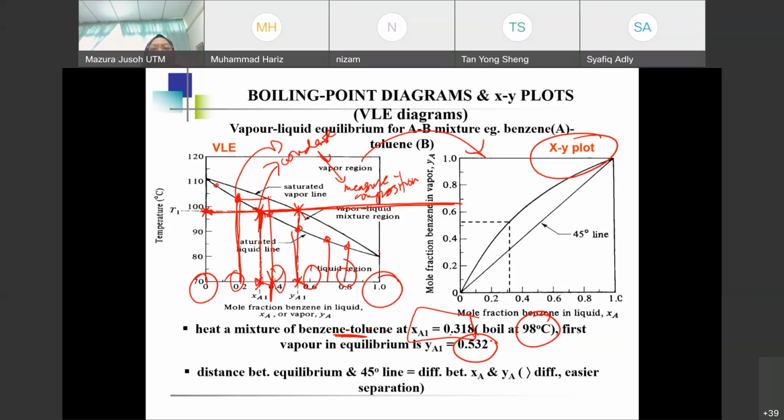so that you can make the saturated liquid line, okay, from the temperature where you saw first vapor, and then the saturated vapor line from the composition of the condensation for each initial composition. So you will have those two lines forming a leaf-like shape, a shape like a leaf. Okay, so that is how you produce the VLE diagram.